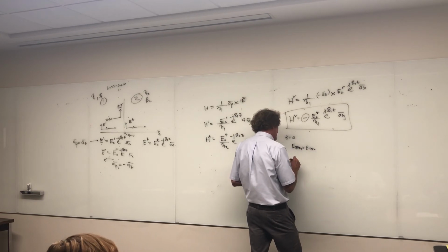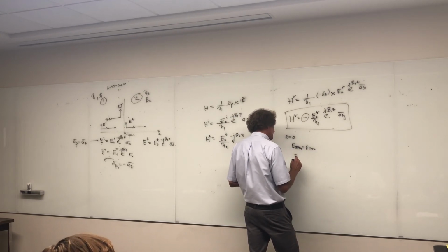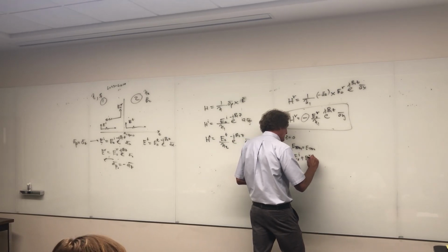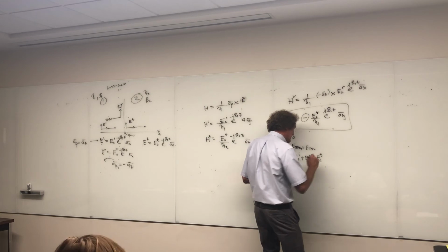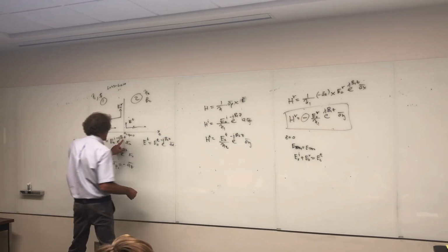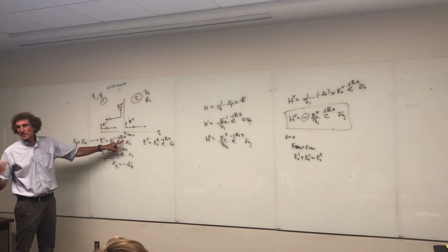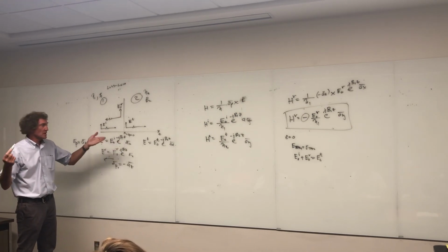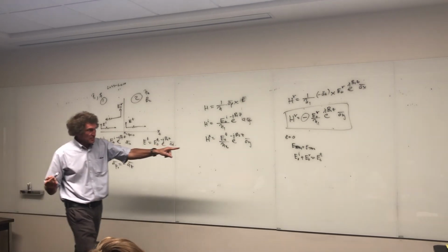And what that means is E naught incident plus E naught reflected is E naught transmitted. Do you all give me that? When you take z equal to 0, what happens to these exponentials? E to the j0 is just 1, isn't it, class? So you just have incident plus reflected equal transmitted at that boundary.